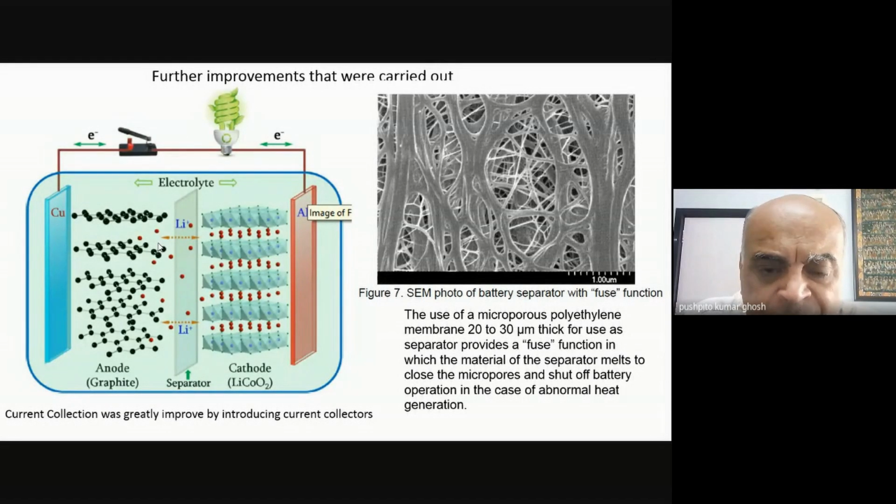And it was found that when lithium plus, let's say during the charging, becomes lithium, then that lithium, which I used originally, which may have been in the form of a flat sheet, doesn't remain like a flat sheet. It forms dendrites, like whiskers of a cat. And those whiskers can go and penetrate to the other side. From there, it can short circuit the whole cell. And because of that, the whole thing can catch fire. This was a huge problem.